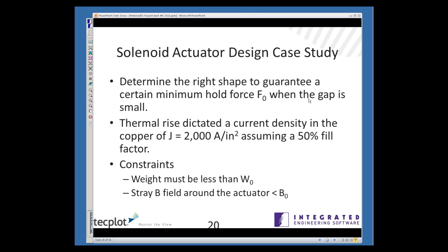In any real-world application, we'll almost certainly encounter multiple objectives and constraints. And one of those is often unwritten, and that is that the insulation maintain its integrity through the life of the product. Towards that end, you'll almost never want to analyze a device with a current constraint on the winding. Rather, if you have that ability, you should always use a current density constraint on the winding cross-section. With that in place, you automatically satisfy the thermal constraint.